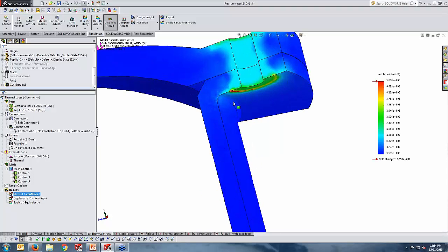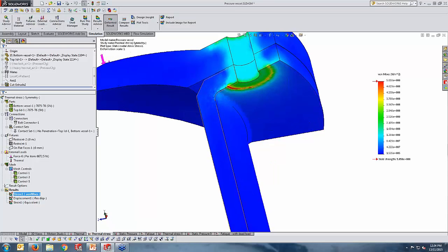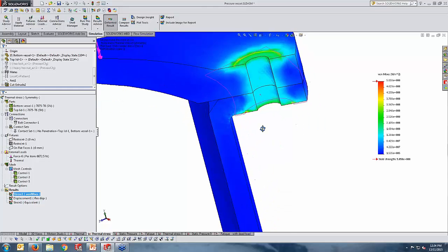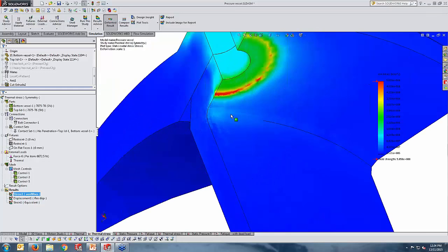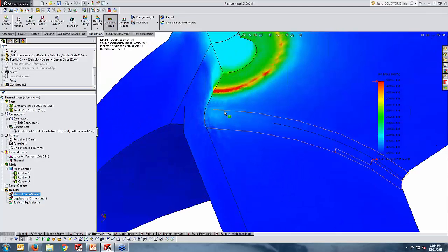Basically, we can see some peaks on the bolt connection area. We can understand the stress singularity is there, and it's not the main concern, and we know it is a numerical fault, or peaks or noise. We can simply avoid it. But the other regions we might be interested in are those regions, where there is a possibility of failure if the